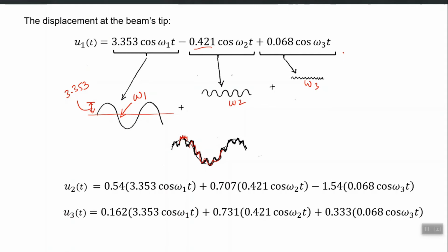So if you plot in Excel maybe for any time t equal to 0 to t equal to, let's say, 20 seconds, you will finally get the combined fluctuation u1 of t, but you can even plot individual terms to see what composes the response, how the response is actually made. If you want to suppress u1 of t, you should focus more on first mode, because that has the highest contribution towards amplitude. If you suppress first mode's contribution, you suppress the overall response, right? So several insights you can get from this analysis, but I'll keep my discussion up till here. I will not go into those practical aspects.